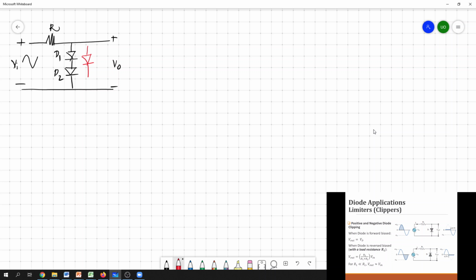because the idea here is, if you want to flow a current through these two diodes, to make this conductive, both D1 and D2 should be forward biased. If one of the diodes gets reverse biased, then you can't see a current flow. So to make this conductive, D1 and D2 should be forward biased.